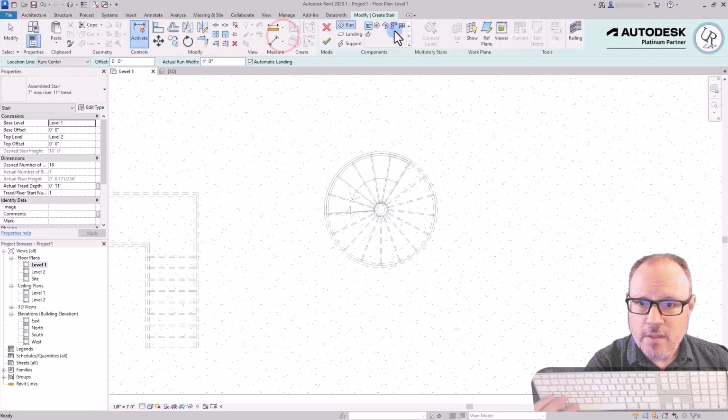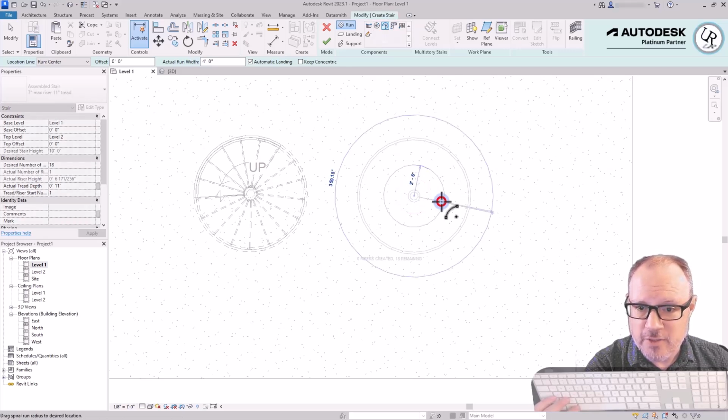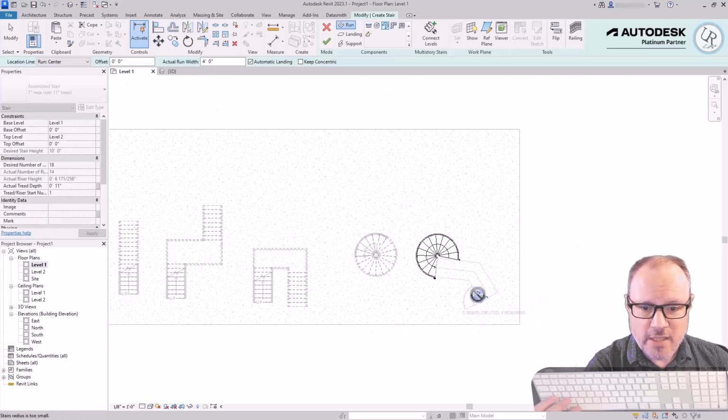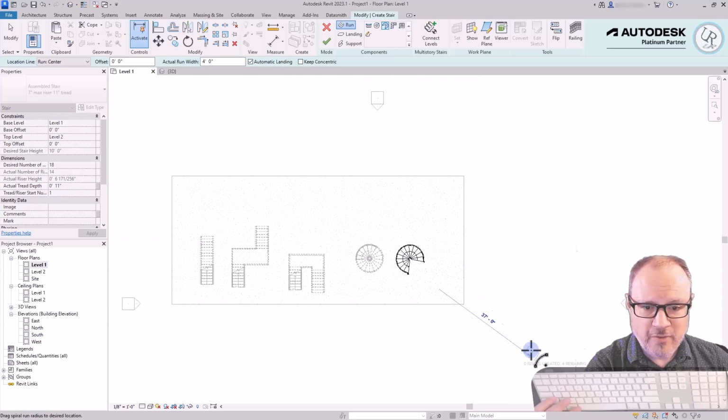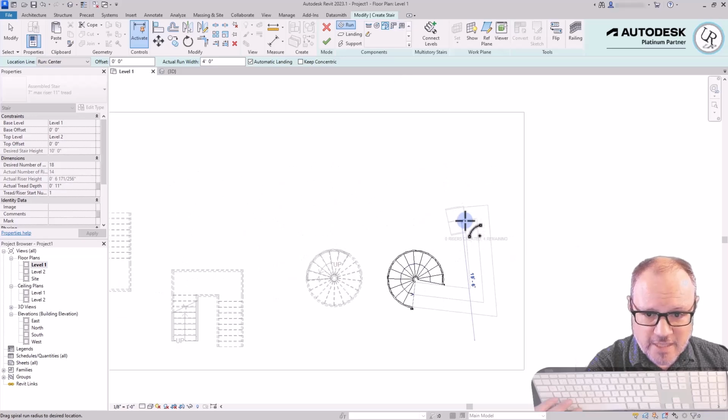Stair tool again, then go into the center and spiral case. Once again, choose a center point and then an initial radius. I'll continue with 2'6". The difference here is you actually do place the risers as you're counting, and it's counted up to 14 risers currently with 4 remaining. And as I left click and I move over here with my cursor, it's going to create a landing between those two segments. Notice how far and complex I can create this landing. It can be at any distance and any length away from that position, to complete that stair design.